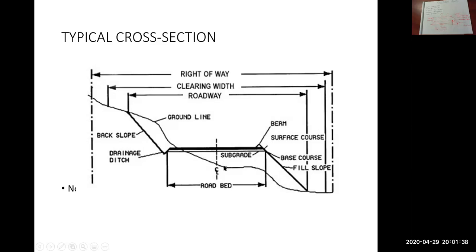Everything below that is your embankment fill, also called subgrade fill. So all of this here is subgrade fill. Everything where my mouse is. So then on the uphill side, if we need the edge of the road to be here, we need a ditch. So that'll be shown on the drawings.